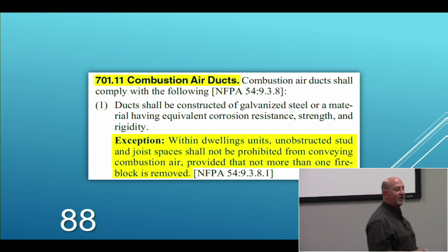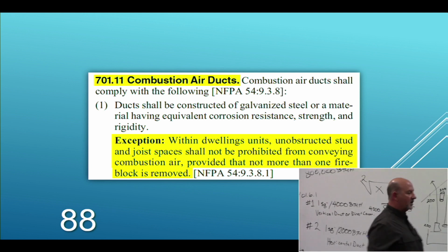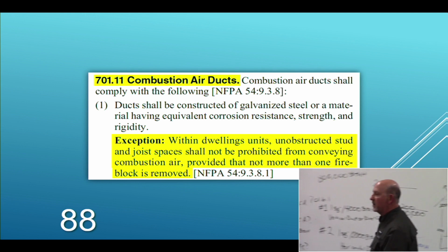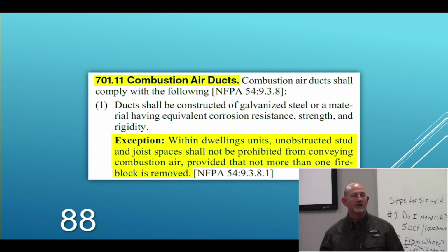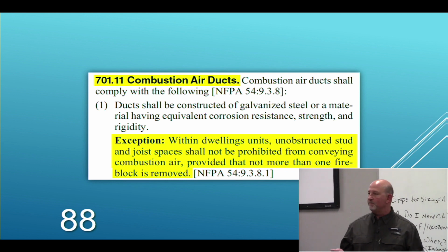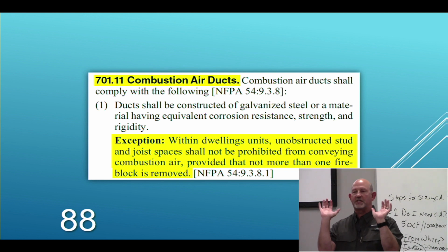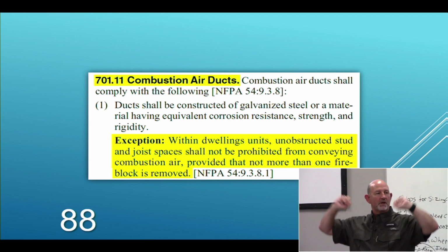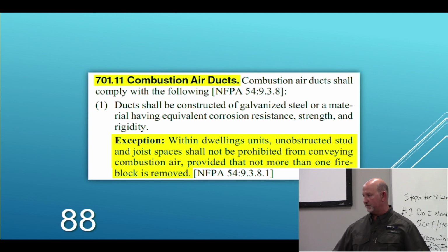So we didn't finish explaining the physics beyond that, but we talked about air wants to move vertically. But just so you know, that's why the code recommends generally, and for years did not give an option for a single. That's why they want an upper and a lower. Because do you agree when that hot air rises, it creates a static pressure on the ceiling, pushing on the ceiling, which pushes the air out the upper, which creates a vacuum in the room, pulling the air in the lowers.